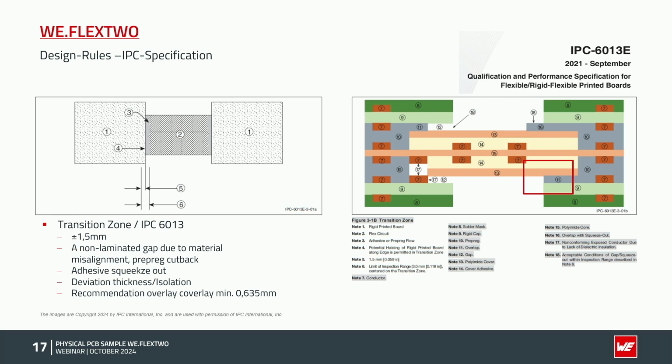0.6 millimeter. Yeah. So remember the design IPC, which is talking about 3 plated through hole, minimum 3.2 millimeters far away from the flex part, and overlap of the cover lay to maximum 2.7 millimeters. So here the recommendation is 0.6 millimeters.